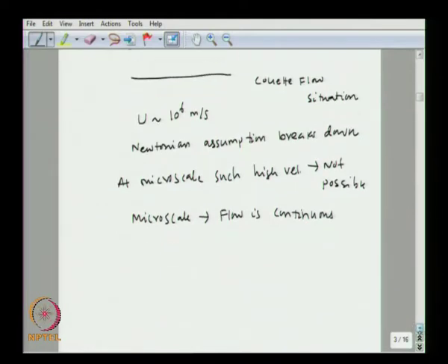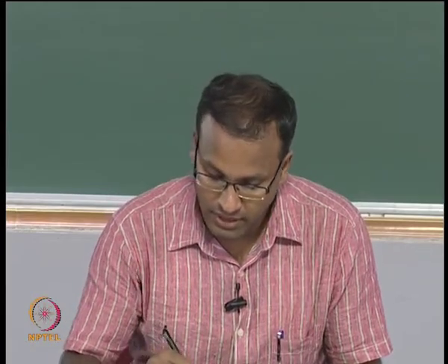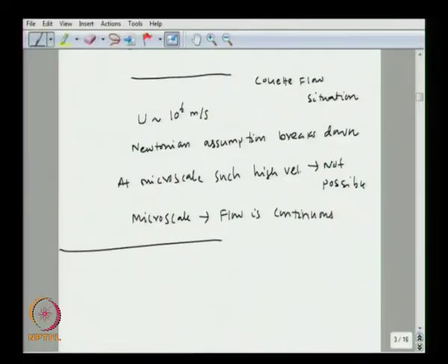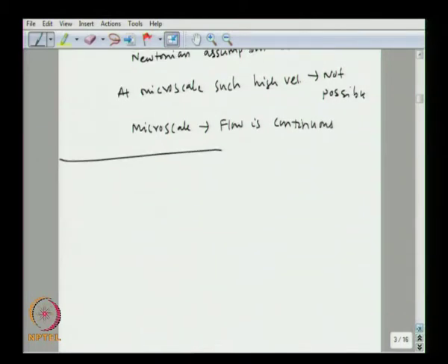Okay. Now, having talked about the liquid flows, let us try to write down the governing equations for liquid flows. In that case you can assume that the fluid is Newtonian. The density for the liquid does not vary that much, you can assume it to be incompressible, and we can also assume that the Fourier law of heat conduction is valid. So, under those assumptions let us write down the governing equations for liquids.